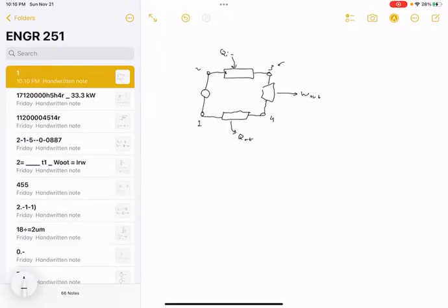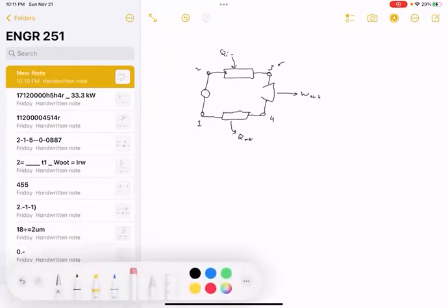Now, of course, it costs energy to run a pump in any Rankine cycle, and we're told, thankfully, how much energy that costs us. We're told it costs us 8.06 kilojoules per kilogram to operate this pump. So if the net work output is 100 megawatts, the total work that we need to be able to produce in the turbine is a bit more than that, because we need to redirect some of that to the pump so that we can keep the cycle going.